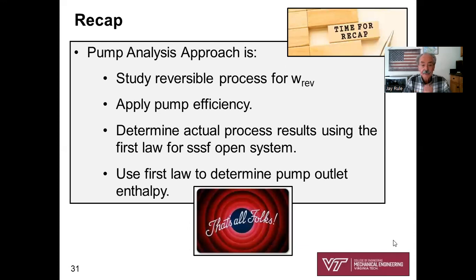Okay, so let's recap the pump analysis approach. What did we do? We studied the reversible process to get W reversible. We applied pump efficiency to get W actual. We were careful with units, and determined the actual process results using the first law for steady state, steady flow. And then finally, if you need to find the outlet enthalpy, use the first law to determine the pump outlet enthalpy.